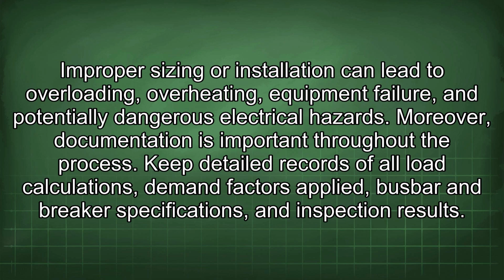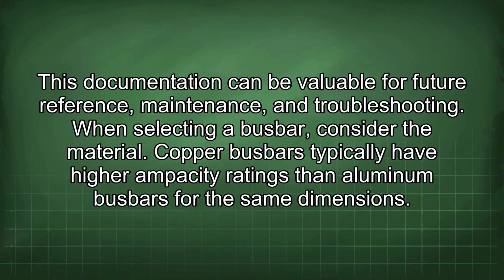Keep detailed records of all load calculations, demand factors applied, busbar and breaker specifications, and inspection results. This documentation can be valuable for future reference, maintenance, and troubleshooting.